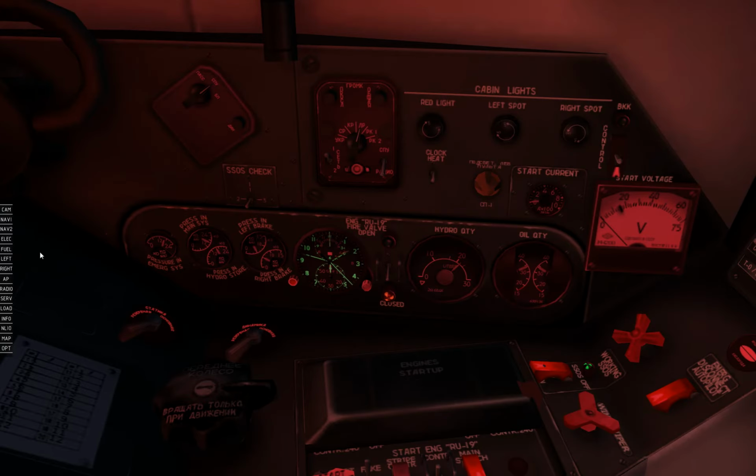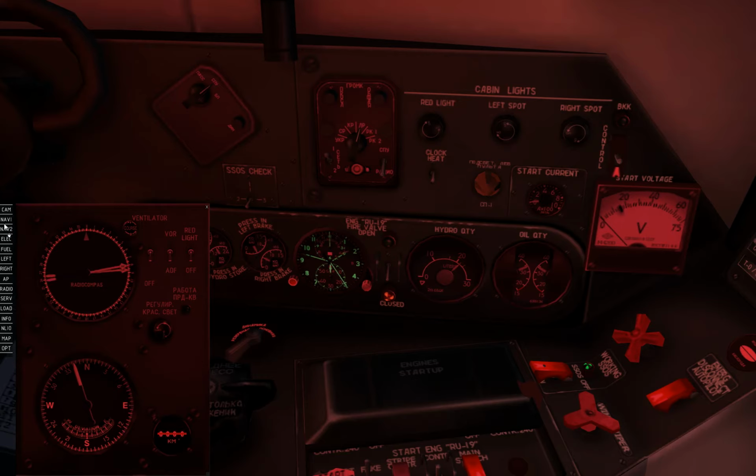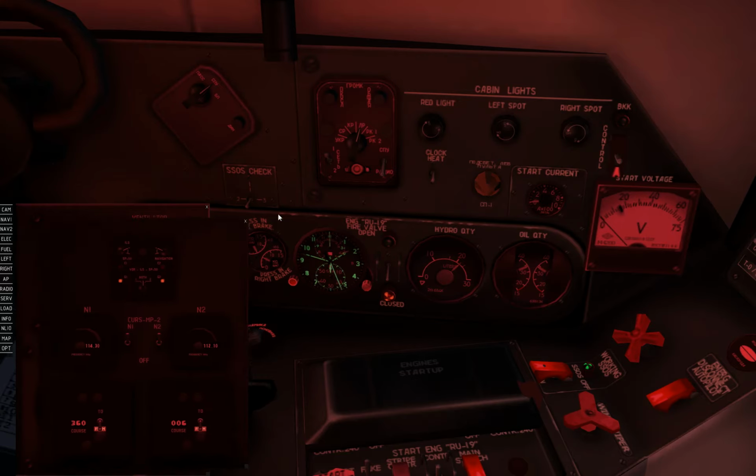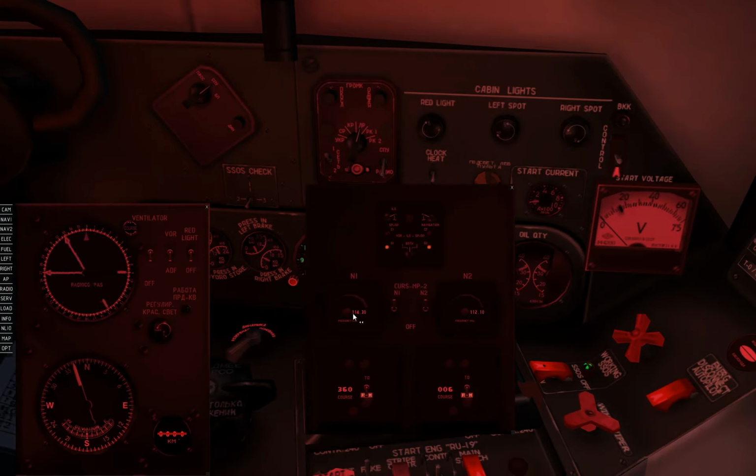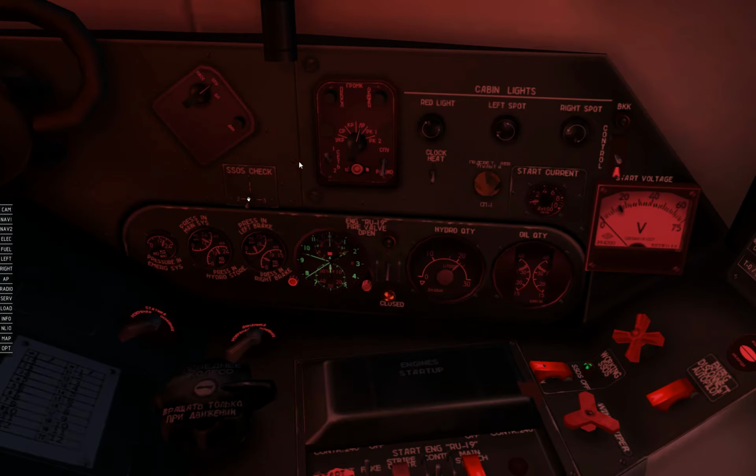Let me go ahead and dial that in using the navigation 2D panels. It looks like I already have 114.3 dialed in over here. So if I switch the audio subpanel to the RK1 or RK2 mode, you can hear the VOR Morse codes. The Morse codes can also be heard on the mode RK2.